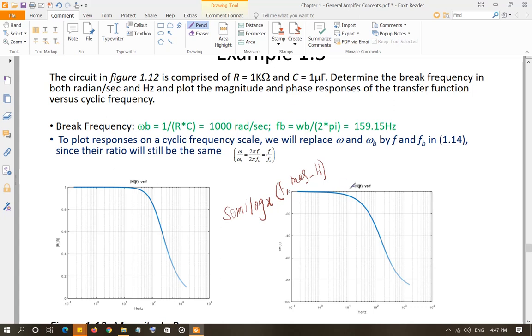In MATLAB also, if you don't remember from other classes, or if you never took any class with me where we discussed that, the complex number magnitude can be found using the abs function. If for example H is your complex number, then abs of H is going to calculate the magnitude of that complex number, and you can assign it to a variable like magnitude underscore H. The phase of the complex number can also be found using a function called angle of H, but angle of H gives you the phase in radians.